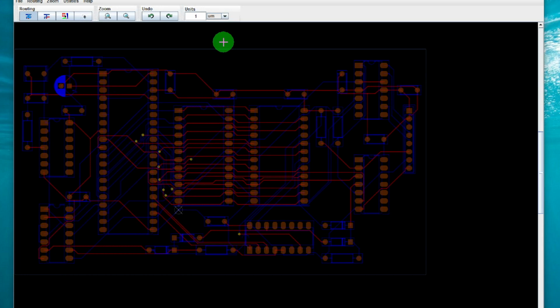It's always better if you've got no vias, but you usually end up with some of them at the end of the day, and it's totally fine. It's just better if you don't have them from a reliability point of view, I think. What you'll find is those vias will appear like they are now, and maybe as the board design progresses and the algorithm runs through the traces, it will decide, oh, I don't want that via there after all. It'll either delete it or move it to another position, which is kind of what it's doing at the moment. It's checking out the via positions and going, can I get rid of that via? If it can get rid of the via, it will do so.